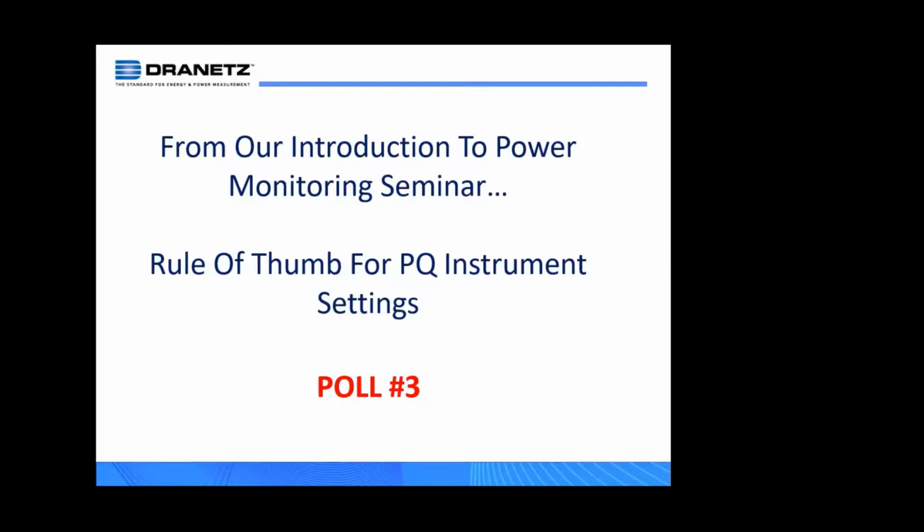If you shout long and loud enough to get them to come out, they'll bring out instrumentation. More than likely, it might be a Dranetz instrument, to be honest with you. And they will connect the instrument to the point of common coupling and measure the voltage over a certain period of time. And if the voltage varies no more than 10%, then the utility is basically going to say that the voltage is within acceptable limits.